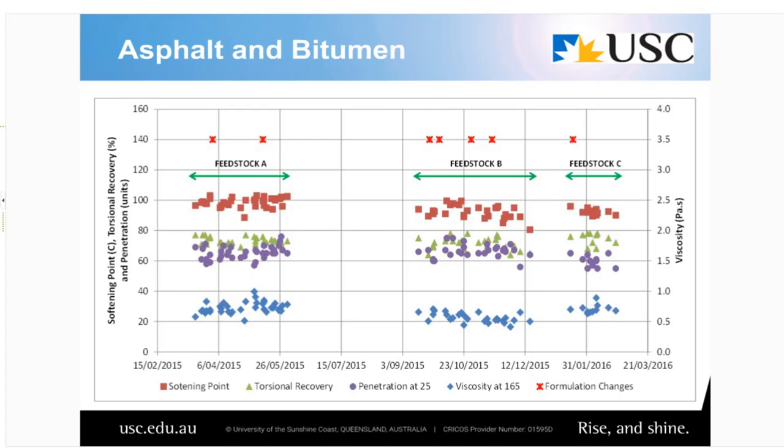But on the flip side, certainly in a hot environment, I would not be endorsing unmodified bitumen in runway surfaces, especially when they're grooved and they're for any significant, and I really mean Q400 or larger aircraft being serviced by that airport.